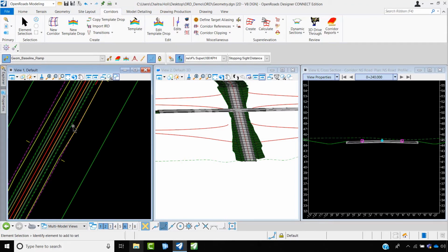So in this template, super elevation flags have already been created. So you do not have to create super elevation lanes for this. Instead of that, I'll skip this option and even this option, because a road template has already been assigned to this alignment.